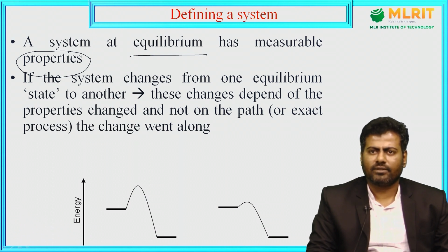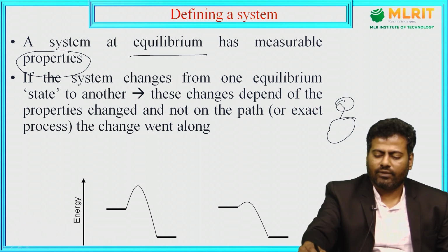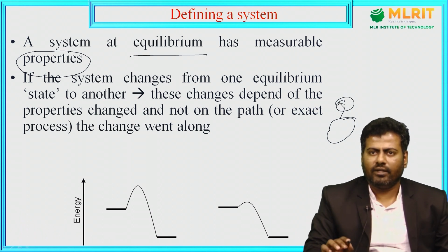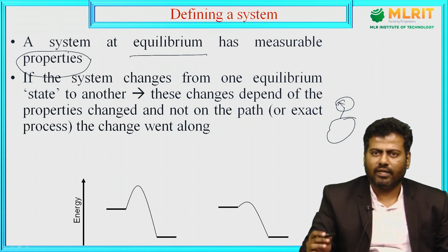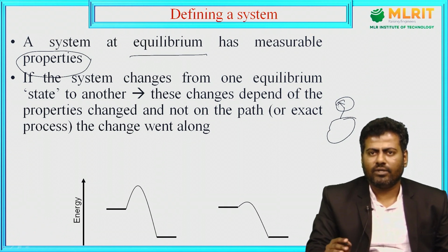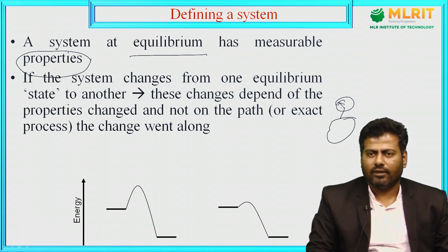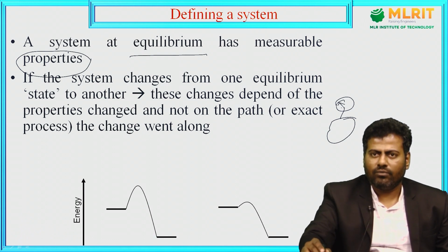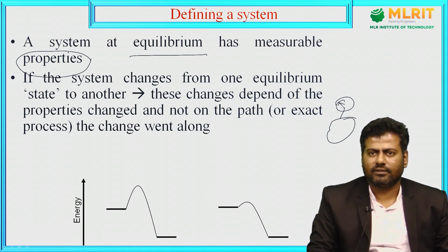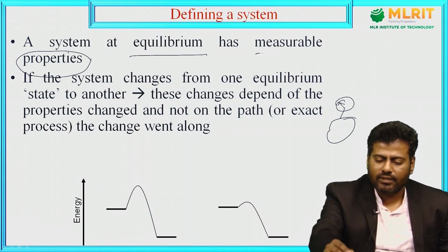In order to measure that, inside the boiler, again I will consider the boiler over here. If I have a pressure gauge in the boiler, during the heat addition process it keeps on changing. The indicator won't show a particular value. But after completion of the process, what will happen? It stops for a while. It shows a particular value for a while, which we can consider as attaining the equilibrium condition. Then I can measure those properties.